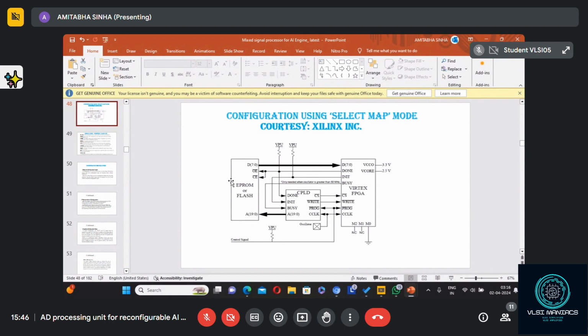Programming the flash memory means, let's say when you have written the Verilog code or any VHDL code, that is there in the computer, in the PC, because initial system design you'll be doing using the PC. After synthesis and all are over, a bitstream file will be generated. That bitstream can be programmed to flash memory by a flash programmer. Using the flash programmer, you can program it. So this flash memory will be completely programmed. Once it is programmed, then you insert it on the board.